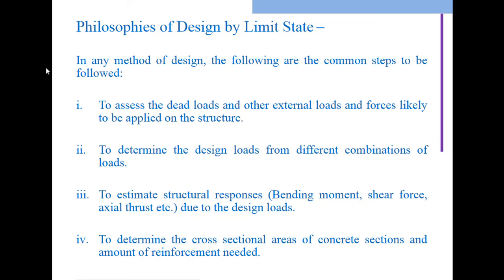Now, the third is to estimate structural responses like bending moment, shear force, and axial thrust due to the design loads. So in limit state design, we only go for design after estimating the responses like bending moment, shear forces, and axial thrust. Without that, we cannot do the design.